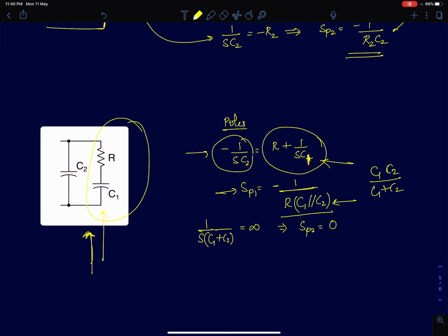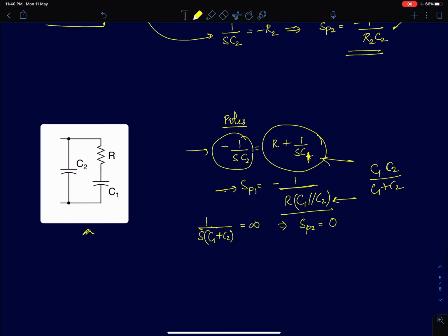The other condition is that whenever we had impedances of this type, we discussed Z1 going to infinity and Z3 going to infinity, both of them going to infinity, that is two of the impedances going to infinity. That happens at a single value of S. If you look at this arm, at DC the capacitor C1 impedance will be blowing up to infinity.